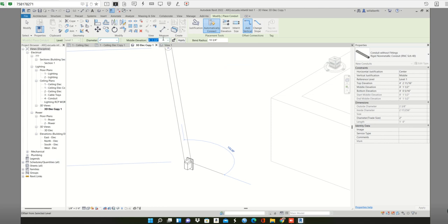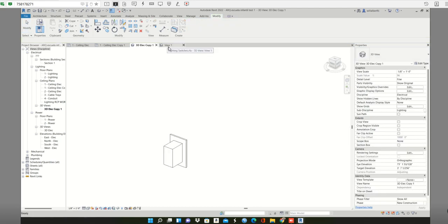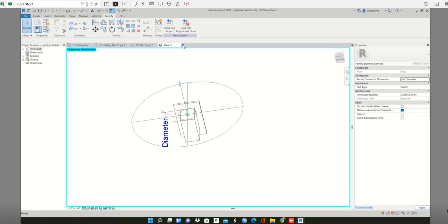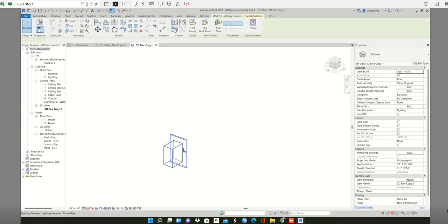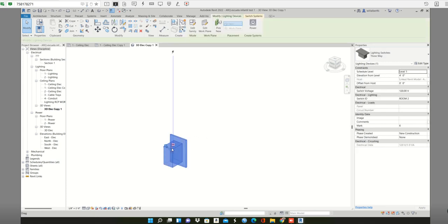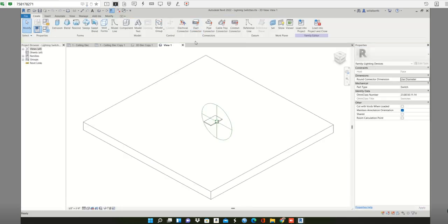You hit switch, then edit family, and then what is the other option that you hit? Let's do it again. It's very important. I love the repetition because that's the only way I learn. I need to write to see it. Okay, let's do it. Select the switch, then edit family. It's like going to open a new Revit. And create, yes, the create option.